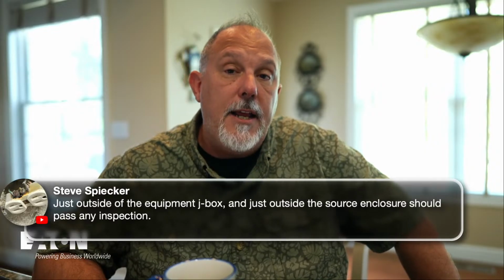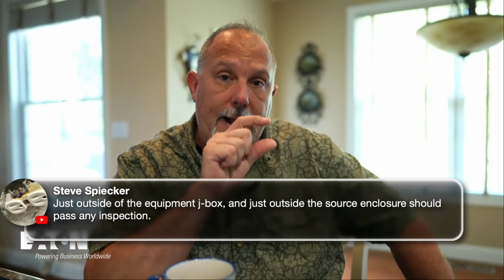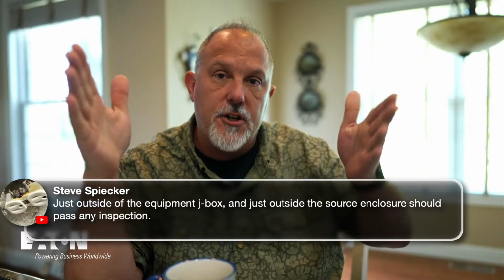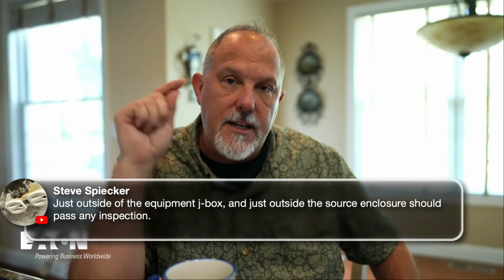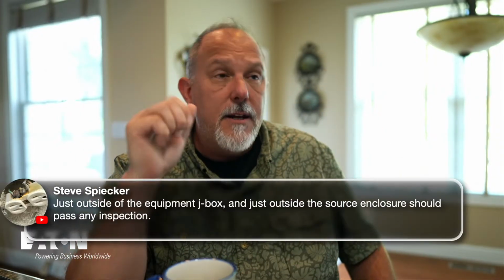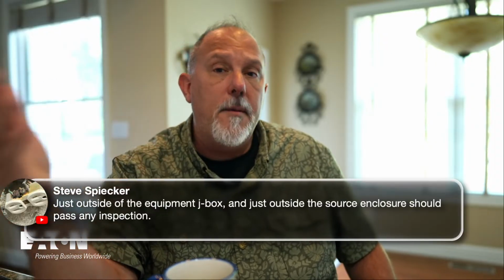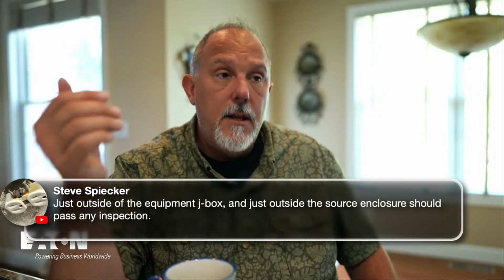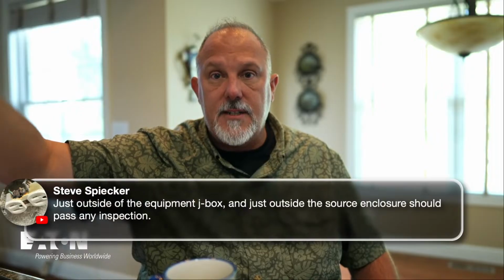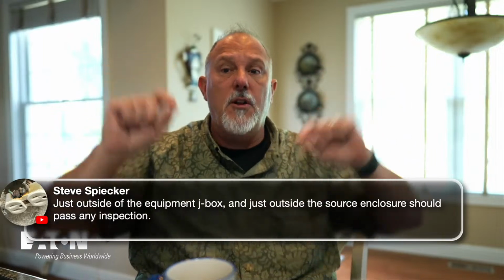Absolutely. That removes any question in anybody's mind, Steve. You take the conductor at 75 degrees C, off of the breaker, out of the box, go to a junction box on a 90 degrees C termination in equipment that's listed for 90 degrees C. Now we can have the debate on whether or not it needs to be listed. I'm not sure there's a requirement that says it has to be listed, but it should have a rating of 90 degrees C. Go to another box that has 90 degrees C, back down to 75 degrees C, and now that longer run is at a smaller conductor size.